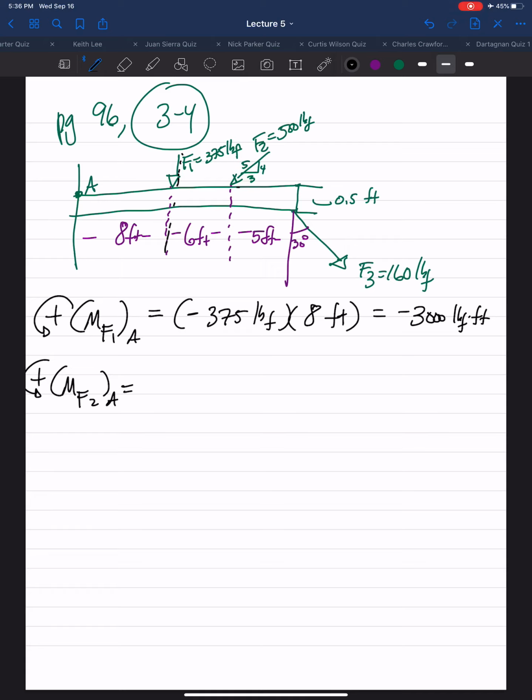The A leg will be right here, and this line of action goes through point A. If the force's line of action goes through the point, then there is no perpendicular distance, so it causes no moment. The vertical leg goes down, and it would have a perpendicular distance. So we would deal with the vertical leg, as we just said, the horizontal leg goes through point A, which will cause no rotation, so no moment.